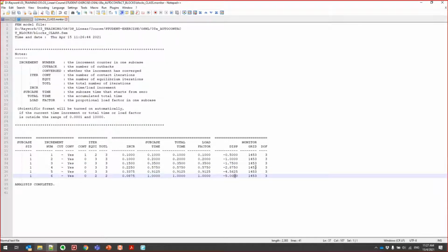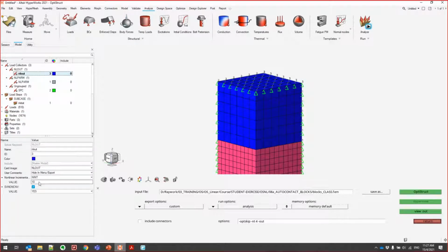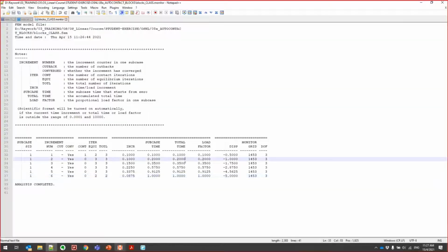Because of the adaptive time increment that we adopt, you can see that even though we request 10 outputs, we won't get 10 outputs, right? So even the number of intervals in here, NL out, NINT 10, we might not get 10 because of the adaptive time increment.